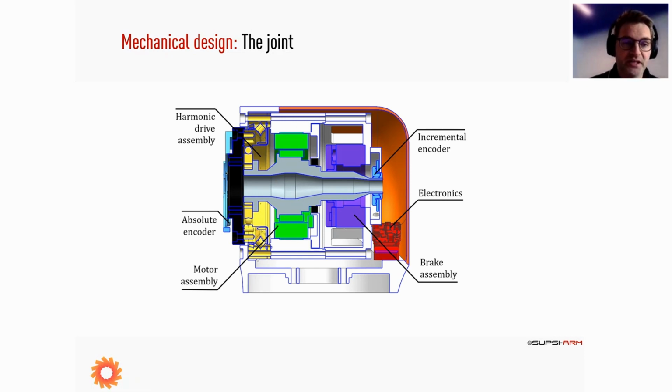We do have a harmonic drive gearbox, which is essentially zero backlash, and so it is very accurate and provides very high ratio within a very compact form factor.